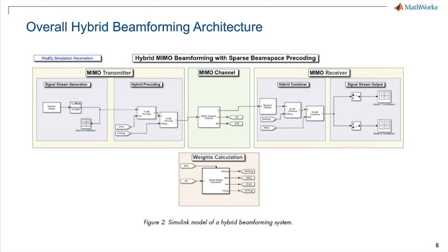So I'm showing you a Simulink diagram, not MATLAB, but a Simulink diagram, where the baseband processing, the digital and RF beamforming, the channel modeling are all implemented in the same environment. Why do I show Simulink? Because, as you can imagine, RF is implemented not in the digital domain or simulated. It's essentially continuous time or kind of analog domain processing, whereas the baseband is discrete time.